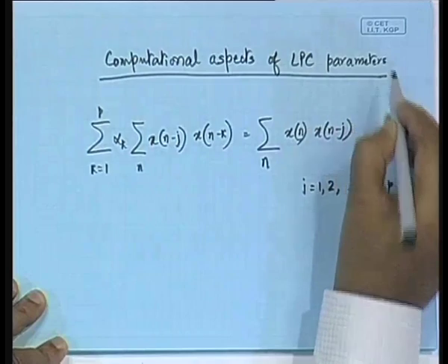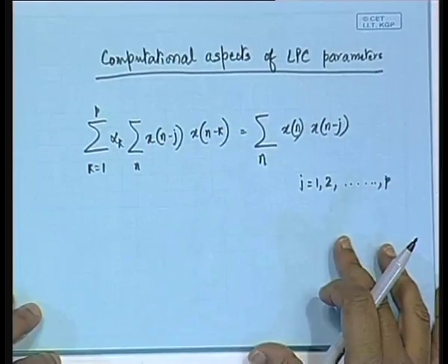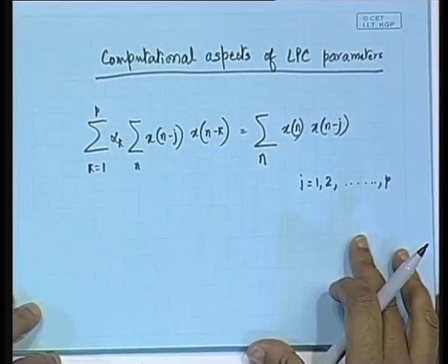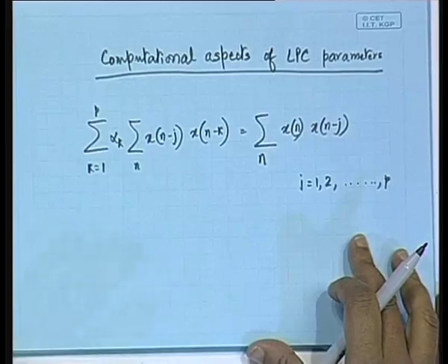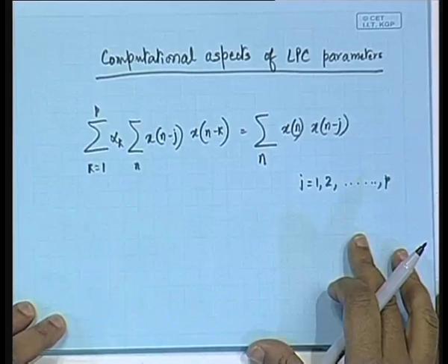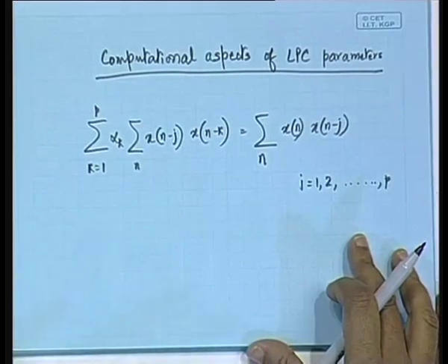There are two very popular, major approaches to the computational aspect of LPC parameters, because the problem is posed such that there are p equations and p unknowns.